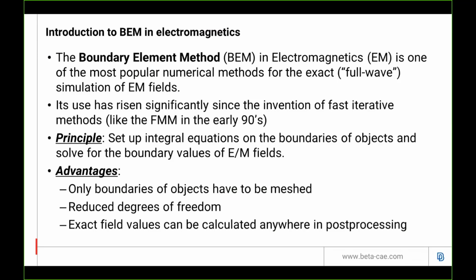And there are significant advantages in boundary element methods. First of all, obviously you need to mesh only the boundaries of objects and not the interior of objects, so you have only a boundary mesh. So that means that you have fewer elements and reduced degrees of freedom on which you have to solve. And finally, you can calculate the exact electromagnetic field values anywhere you like without being bound to a mesh in the post-processing stage.